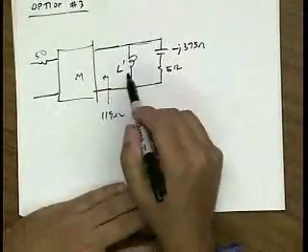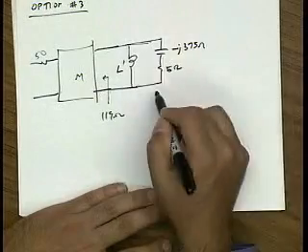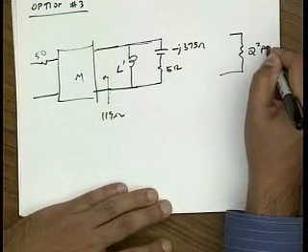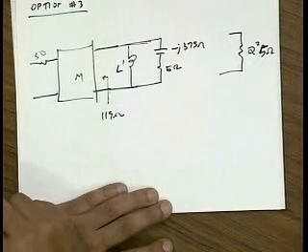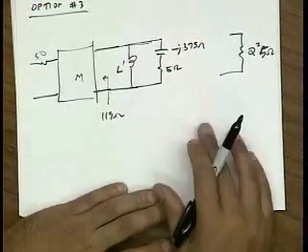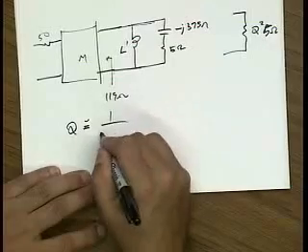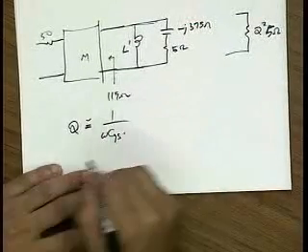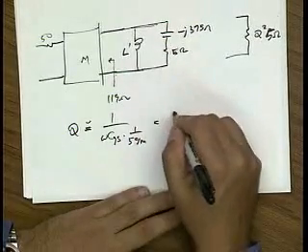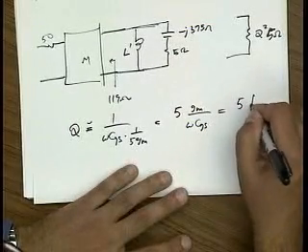Well, remember, if I put an inductor in shunt here, I can do a series to parallel transformation. So the equivalent parallel resistance seen here in resonance just looks like Q squared times 5 ohms, right? So the question is, what's the Q? The Q is simply 375 divided by 5. But more generally, I can write the Q of the input device as approximately 1 over omega C_GS times the R, which is 1/5 g_m, neglecting the poly resistance. So this gives me 5 g_m over omega C_GS, or 5 times f_T over f.